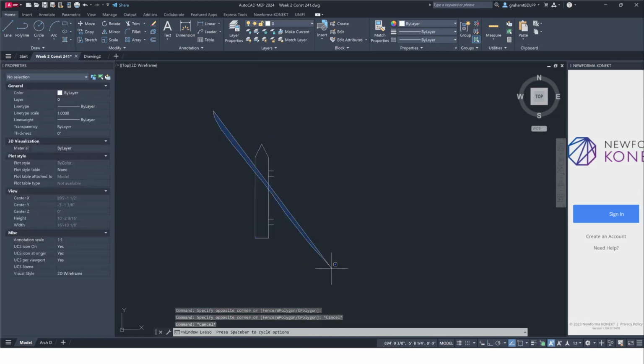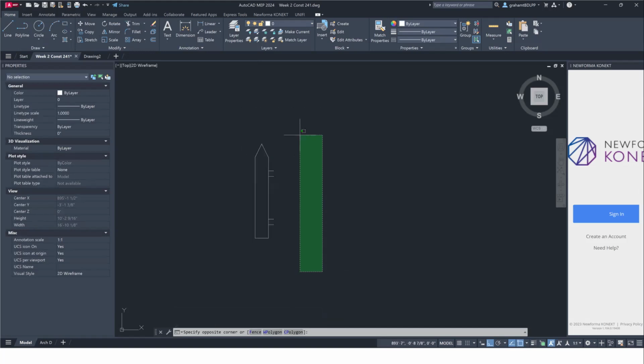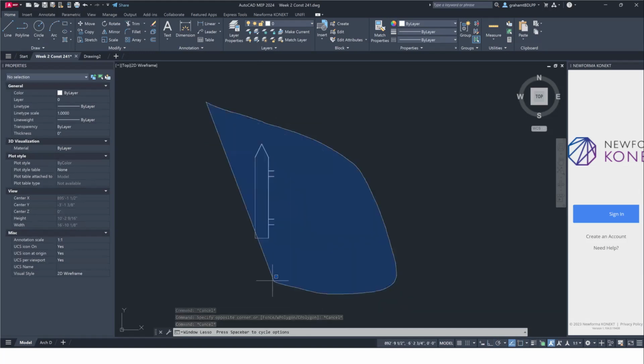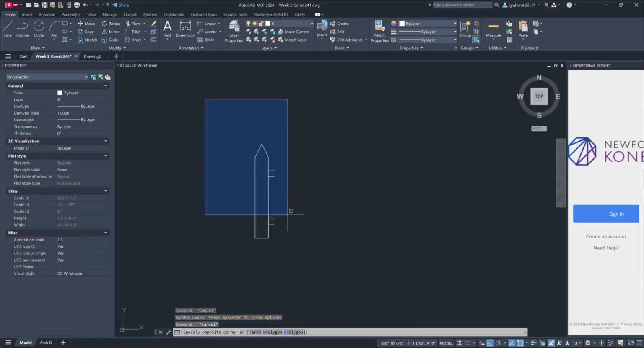From left to right, you have to encompass the whole thing to get it selected. From right to left, you just have to touch it. But a lot of times you may end up grabbing more items than you want when you grab right to left. Okay, two different options. And then again, if you click and hold and get something like this, it works. But if you drag this back across itself, it will deselect. Whereas when you window an item, it windows or it doesn't, right? So any questions on that, just about selecting?